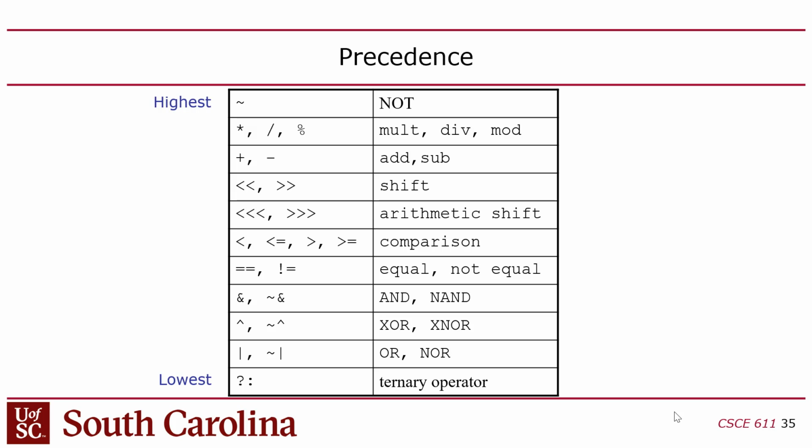So if you say Z equals equals Z, false. They're not equal. And the reason it'll do that is because in real hardware, you can't compare two floating signal values in digital logic. It's impossible. However, if you use equals equals equals, and you say Z equals equals equals Z, that'll be true, because that one is designed for simulation purposes where it'll allow you to compare two non-binary values. You can compare X's and Z's for equality and it'll work, but only if you use the equals equals equals.